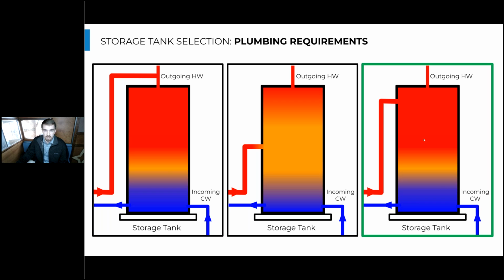And I would definitely say that the third way here is my preferred. I'll explain why, but I'll just go from left to right here. So the common theme is that we have stratified storage: hot water in the top of the storage tank and cool water in the bottom of the storage tank. Those are separated really thoughtfully because it allows the heat pump to suck in that really cold water that makes it run efficiently, and it provides a greater storage capacity.